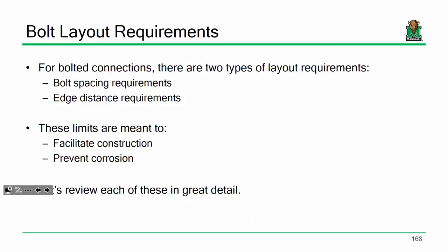All right. Everybody good so far? All right. I think I'm going to call it for today. What we're going to do next time is this. We talked about bolt capacity and bearing capacity, but we actually didn't talk about some really simple stuff, things like laying out the connection. If I do a bolted connection design and I say, okay, we need 8 bolts for that connection, that's not enough to actually go out and fabricate it. I need to know how to space out those bolts. I need to know how far they can be from the plate edge. So we need to talk next time about bolted connection layout.